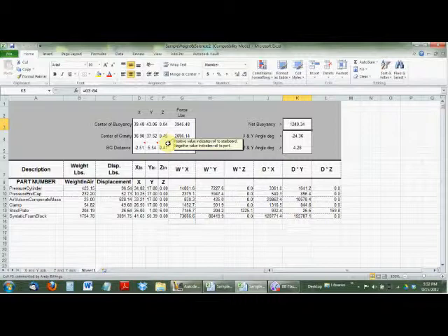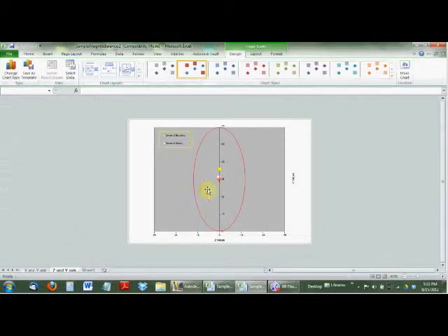The positive value indicates roll to starboard. So 0.41 is a positive value, and so if you turned yourself around and this was the front, you would see that this would be the right side, although it's your left side now, and that this thing would be rolling to starboard.